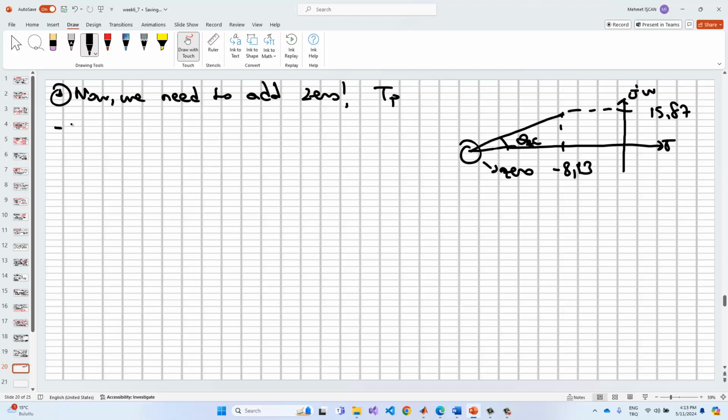And so the total angle is the minus 198.37 degrees in here. Because we have the 3 poles at the open loop system, and also we have the 1 zero, and then we can collect the whole terms in here, theta 1, theta 2, and theta 3. Just remember that this question.